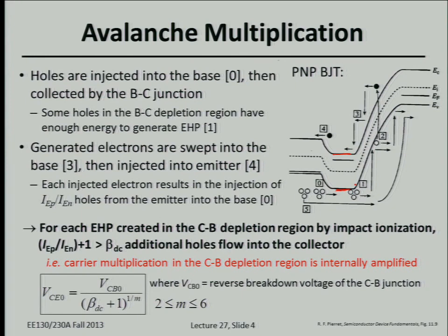So let's go through this a little bit slowly. Ordinarily, when avalanche occurs in a p-n junction, you have to have a relatively high electric field in the p-n junction depletion region. So that's what's shown here. In this region, you have a relatively high E field, so a relatively steep energy band diagram, because within, let's say, a typical mean free path, the carriers can gain enough kinetic energy so that when they scatter, they can lose enough energy to generate an electron-hole pair.